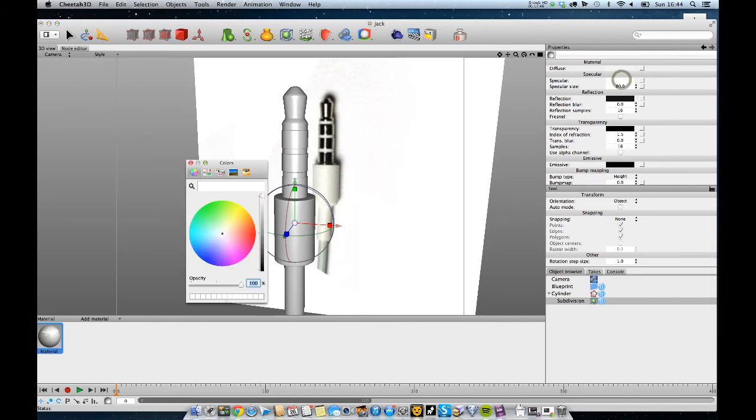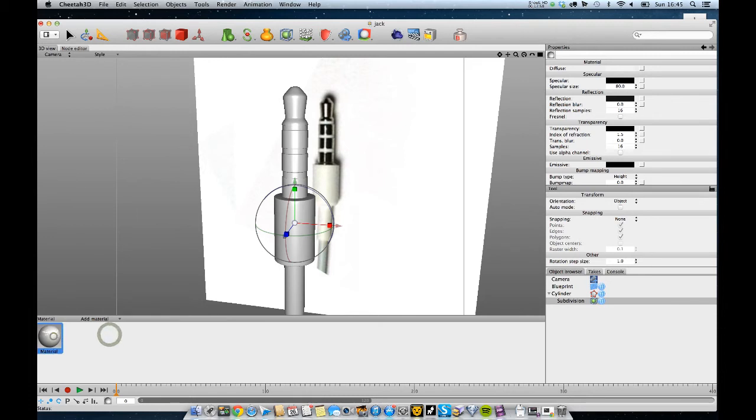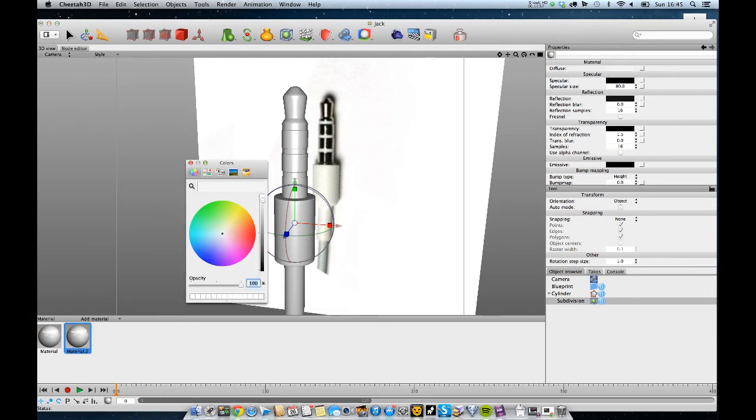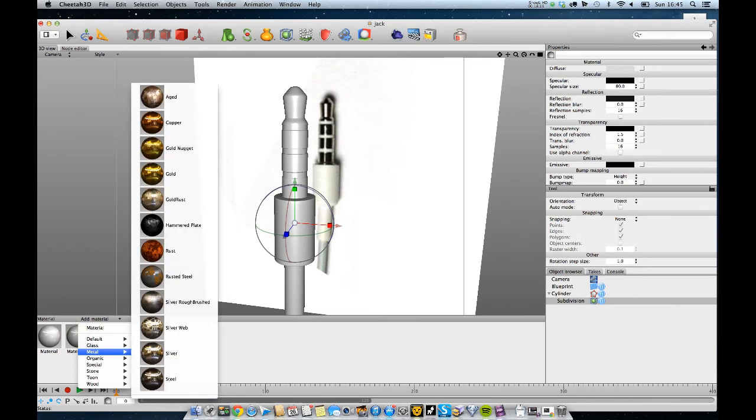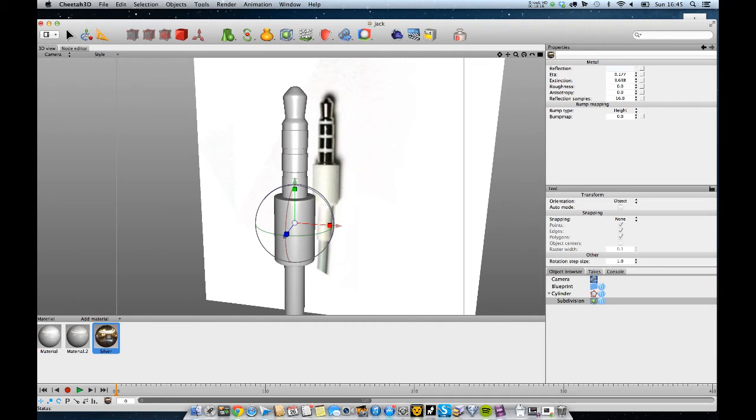I'm going to just turn the specular off. Set that to black. Okay. Copy that material. Paste again. We've got just down here the cable's slightly grayer. So I'm just going to drag that colour down, the diffuse channel down a little bit. That's that one. We'll use this white for these areas here, I think. And we'll add one of the metal. We'll use silver for the actual chrome. It's time to start applying those.